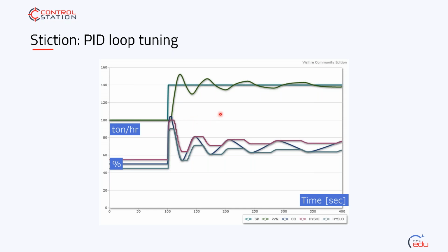If it's 2%, you slow it down by another double, 3%, etc. Is anybody in the audience thinking, if I increase my integral time by double, it's going to get radically different, and you're going to lose the ability to accurately control? But what you are going to do is just change the frequency of oscillation into a longer cycle. The oscillation is still going to be there. The lack of control is still going to be there. You're just going to spread it out over a longer period of time.